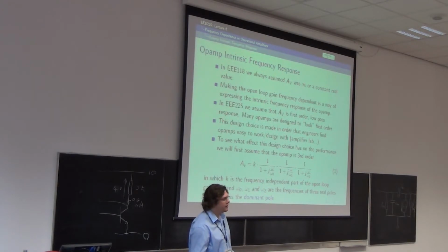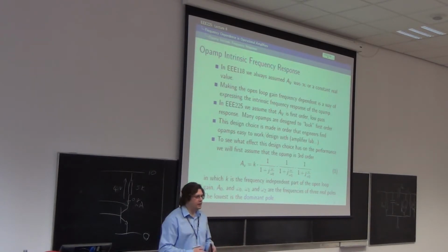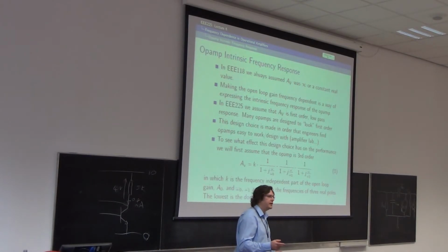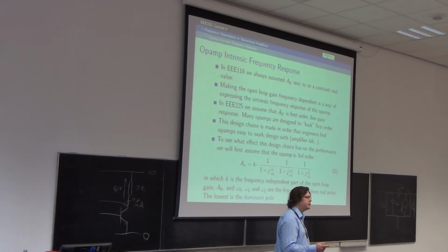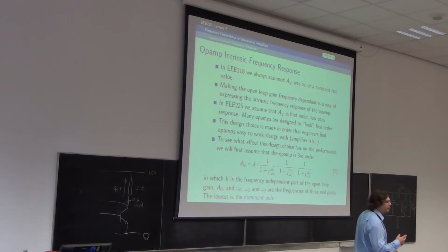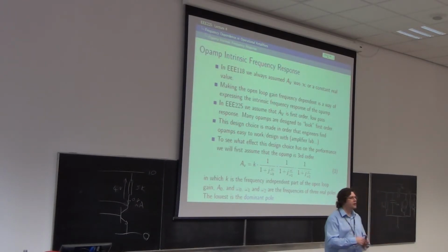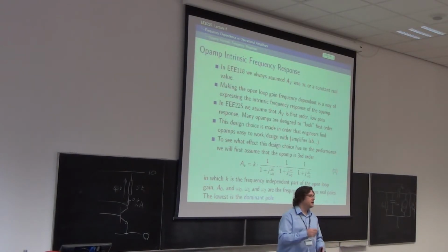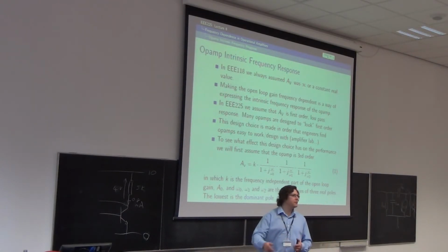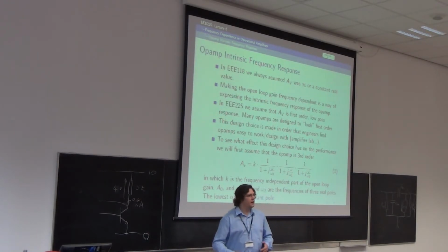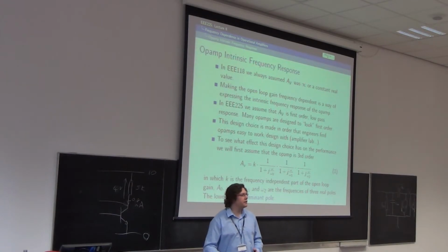And part of the amplifier lab was that we would get the rise time. This was day 2, exercise 1. Get the rise time of the op-amp, work out what its tau was, compare it with the gain bandwidth product, look at the phase shift. Phase shift's 45 degrees, your rise time's 2.2 times your tau, and the gain bandwidth product all adds up. You can say, oh, it's a first order system. Happy with that? Or do you want to hear that again?